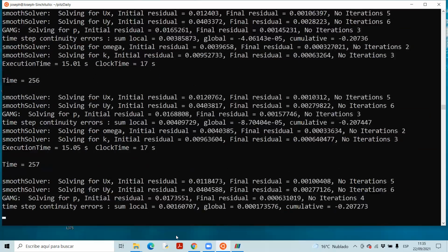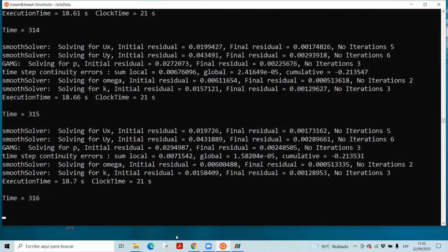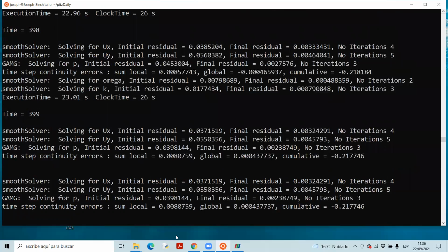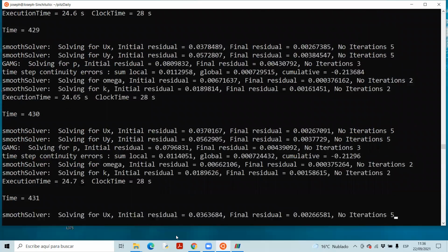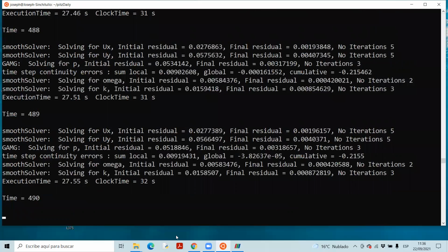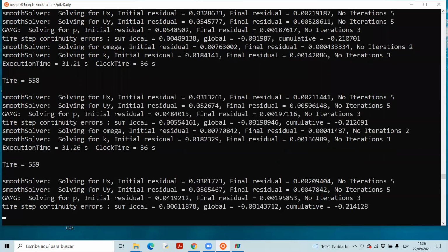Now you can see my simulation starts working, and my convergence criteria for omega, k omega, velocity and pressure are 10 power negative 20. Now it should run, and the end time for this case is, let me open one more Ubuntu terminal and explain all these things there.